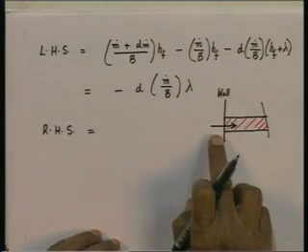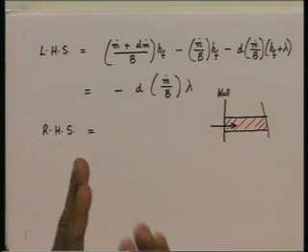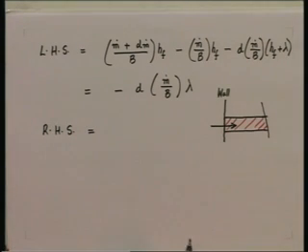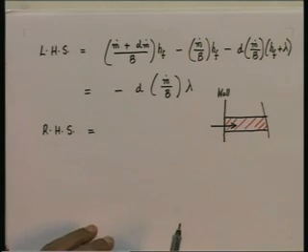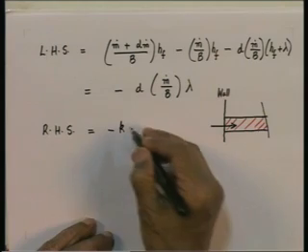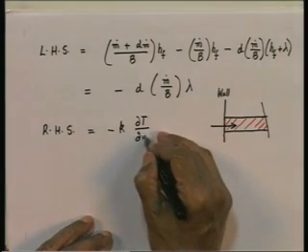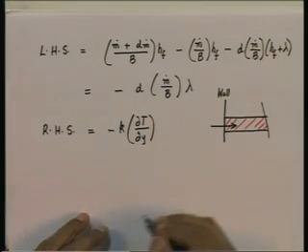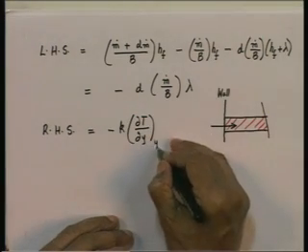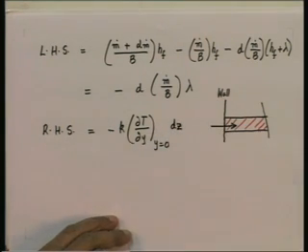So, this is where the heat transfer to the control volume takes place, and since it is a fluid flowing across a wall, we know from our study of convection that the rate of heat transfer will be minus k, Fourier's law will apply at the wall, minus k dT/dy at y equal to 0, multiplied by the area dz, and we are taking a unit width.